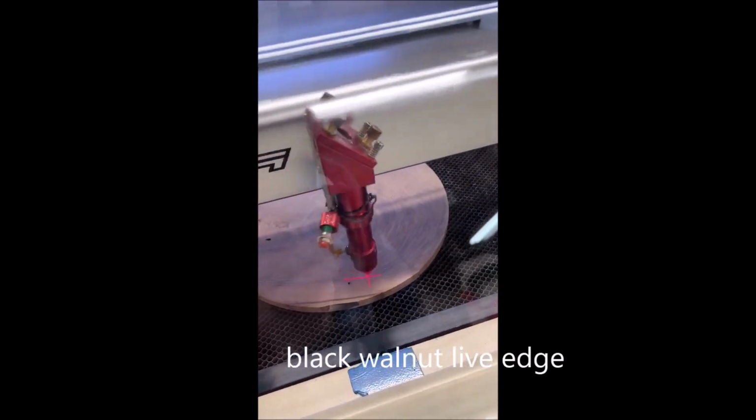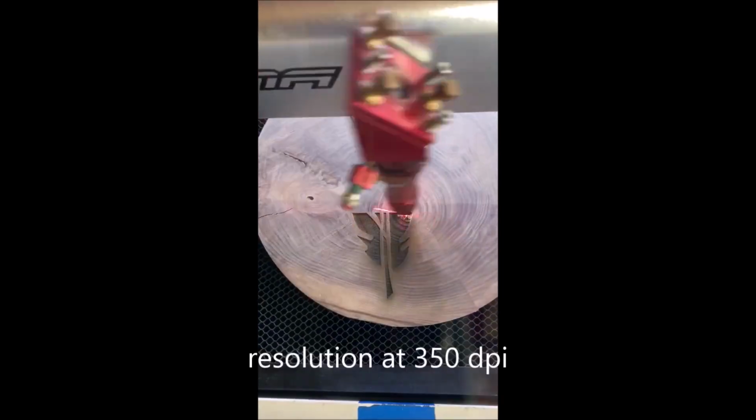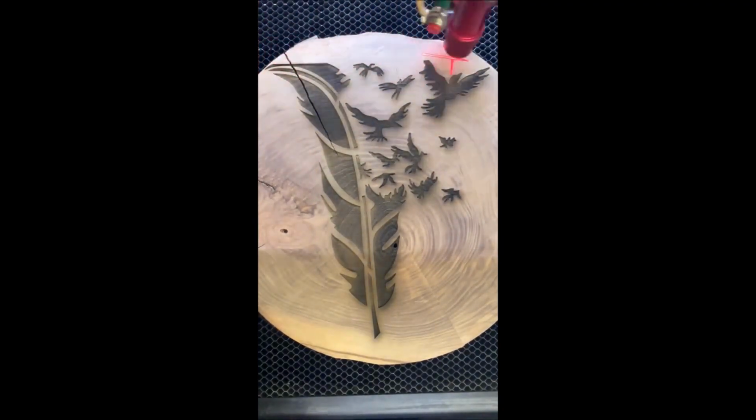I mentioned earlier I want a deep engrave, and what I meant by that is that I'm going to be engraving this at about 350 dpi. I want it down a bit so I can paint those parts that are engraved. When I say down a bit, I want the engrave to be deep, like about 1/16 of an inch.